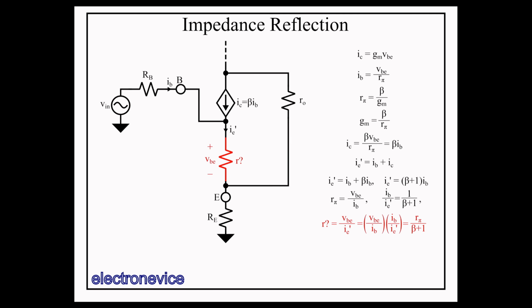In many cases, it can significantly simplify the circuit. Note that the impedance is inserted in the emitter such that it's working within the loop formed by RO. Don't put it after the emitter where RE is. Of course, if you're working with a circuit where you're able to ignore RO, this simplifies things.